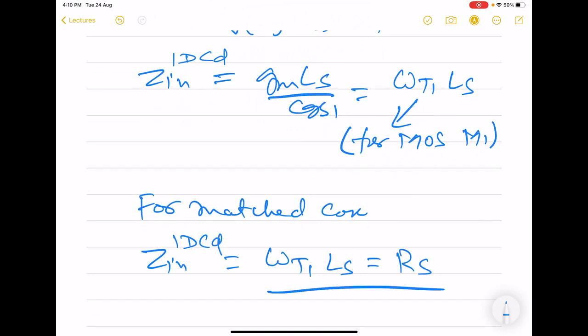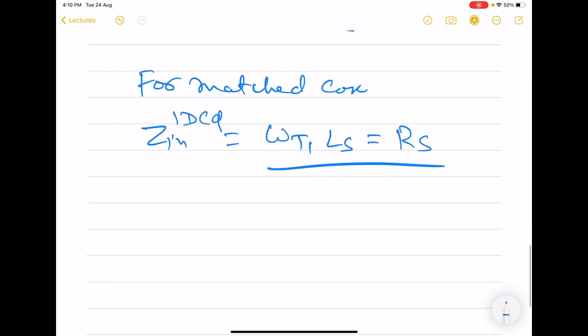We will be using this equation in subsequent derivations. Here also we find that a real impedance is possible, but only at one specific frequency. So this Cascode LNA is also going to be narrow band. Now we will try to find out the noise factor.